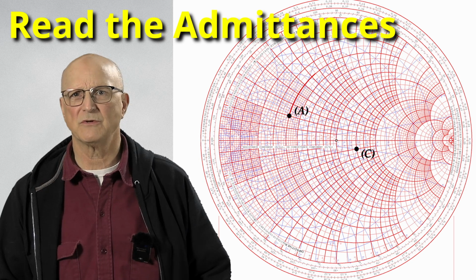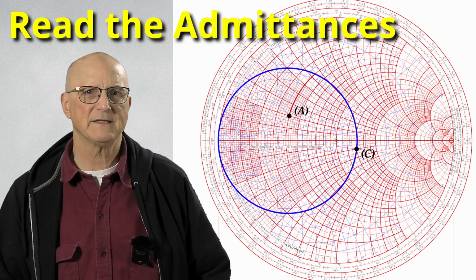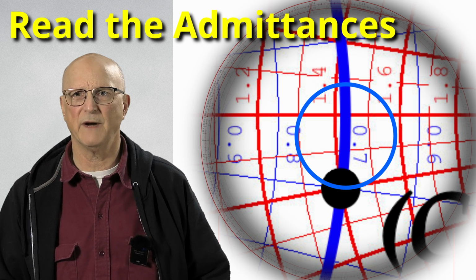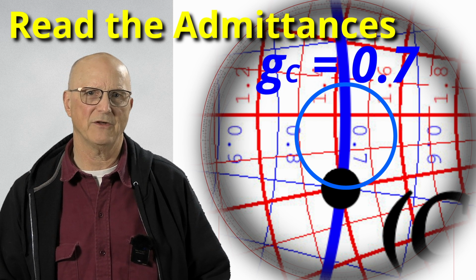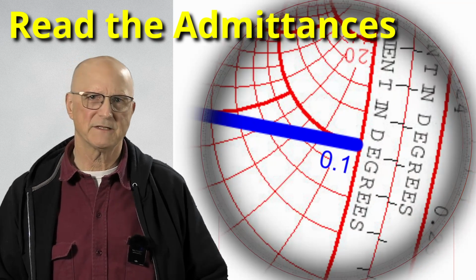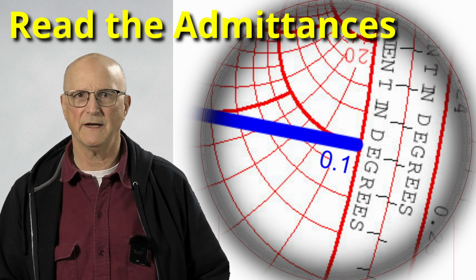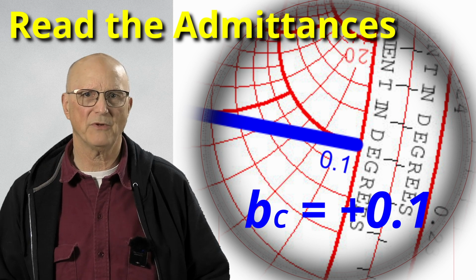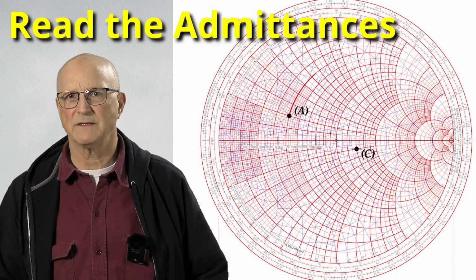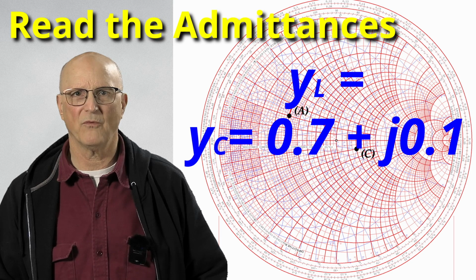Now, let's go to the load's conjugate normalized impedance dot to do the same thing. I see the 0.7 constant conductance circle passes through my dot, so the conductance value is 0.7. I also see that the plus 0.1 constant susceptance arc also passes through my dot, so the susceptance is equal to plus 0.1. The load's normalized admittance is equal to 0.7 plus j0.1.